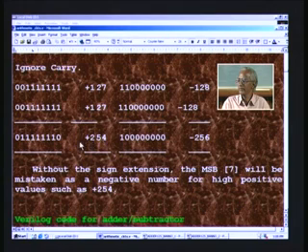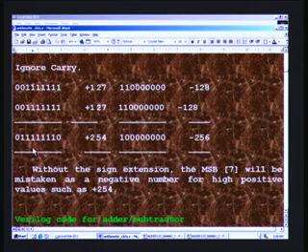So, instead of interpreting it as plus 254, the system will be reporting it as minus something else. That is not a desirable thing, and hence the need for extension of the MSB to the next location, and that is why we have a sign extension. That is the meaning here.